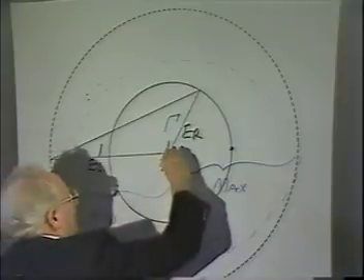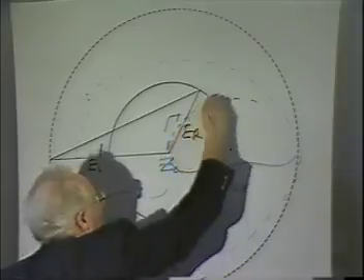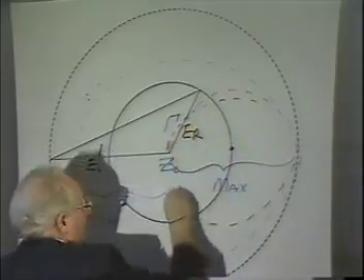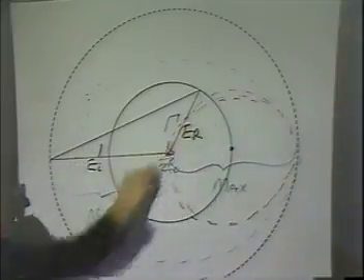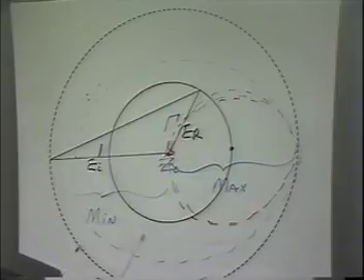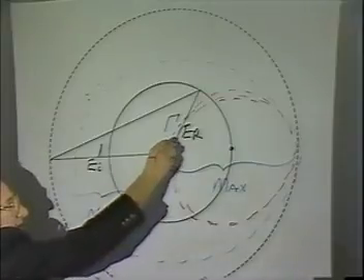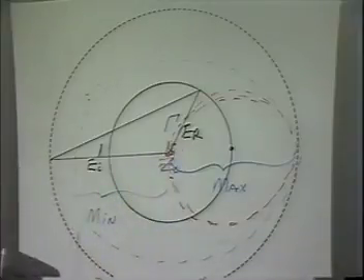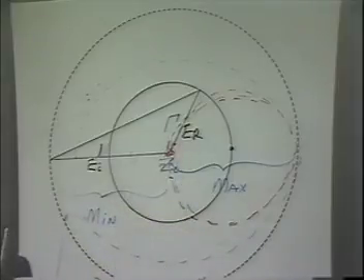If I have this circle drawn here then, that would be called the Z0 circle. Every point on that circle is 50 ohms. But if it's any point other than this, it'll either have an inductive component or a capacitive component. But that's it. The 50 ohm circle.